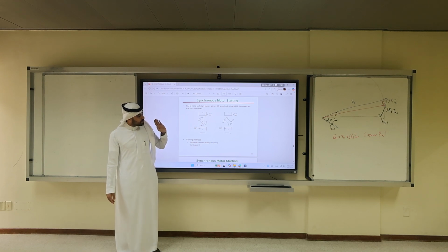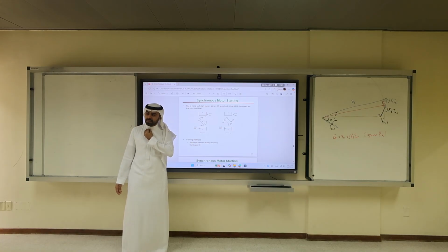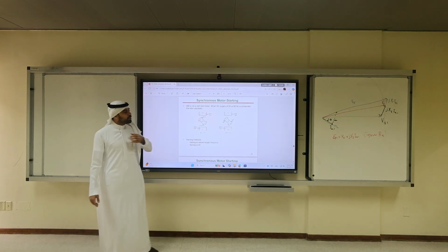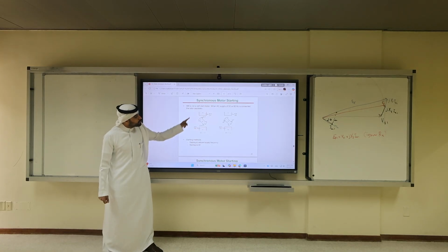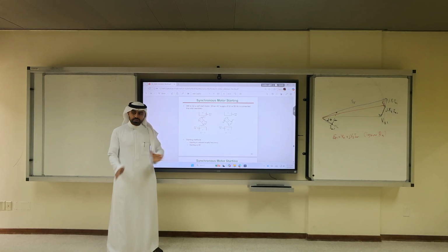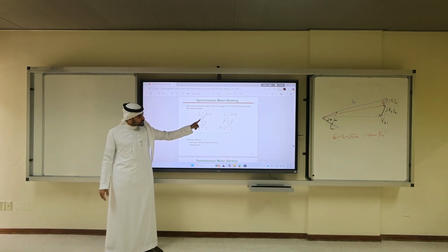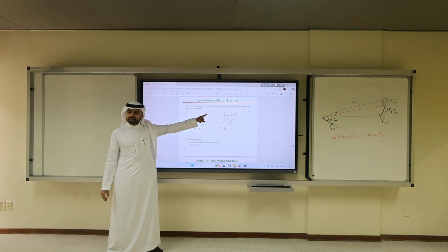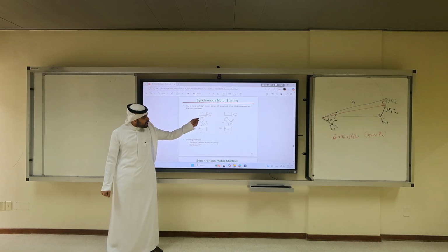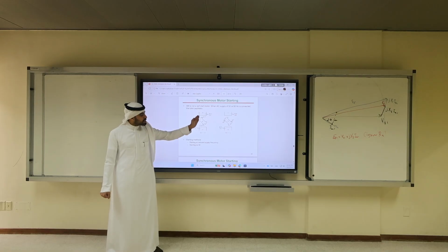Why does the magnetic field rotate? Because this is a uniform rotating magnetic field. This is the technical answer, uniform RMF. A uniform RMF would rotate at 3600 RPM. However, the rotor at standstill has a uniform DC excited field. If I'm not spinning it, the rotor will be at speed 0 and the stator field at 3600 RPM because it's at 60 Hertz. In order for me to align the south and the north with the torque angle and synchronize both of them,